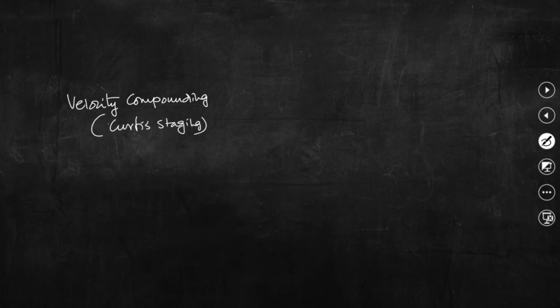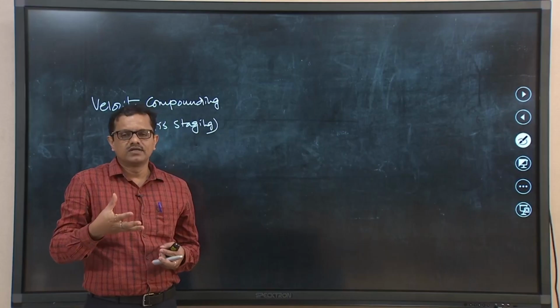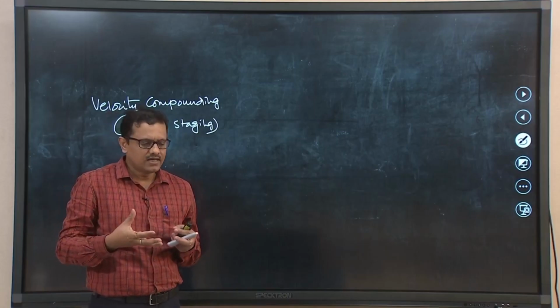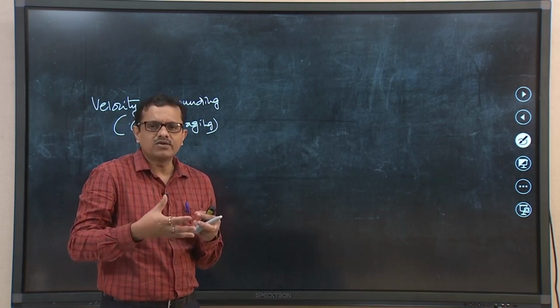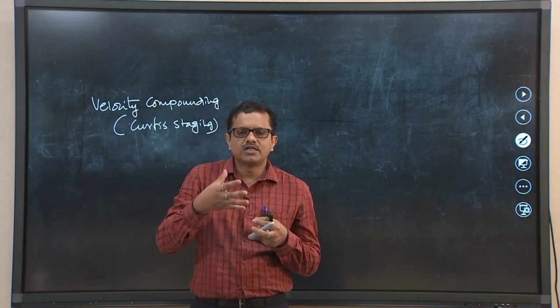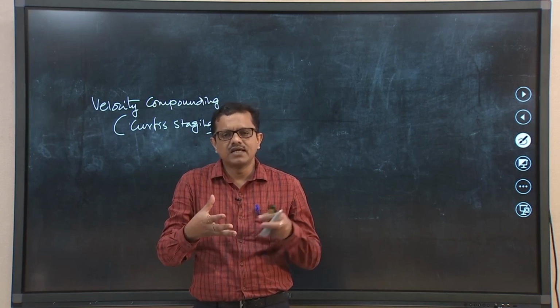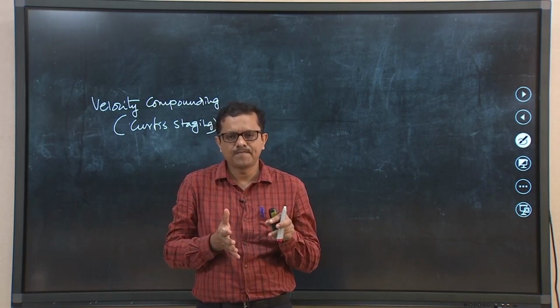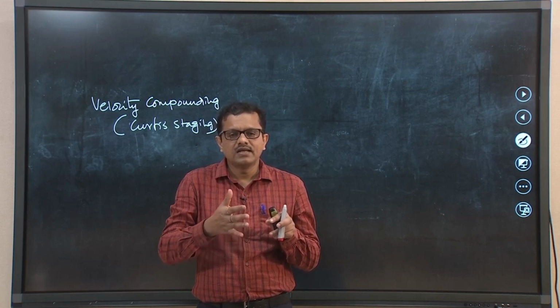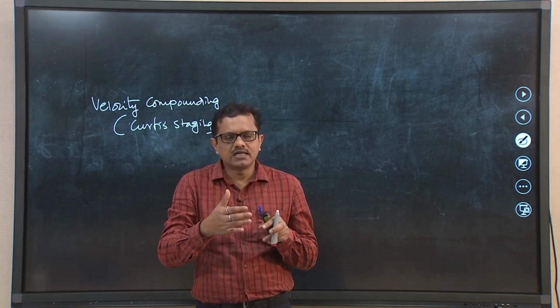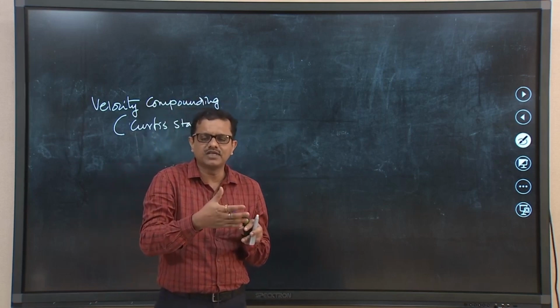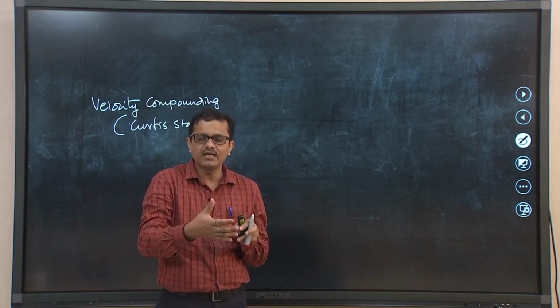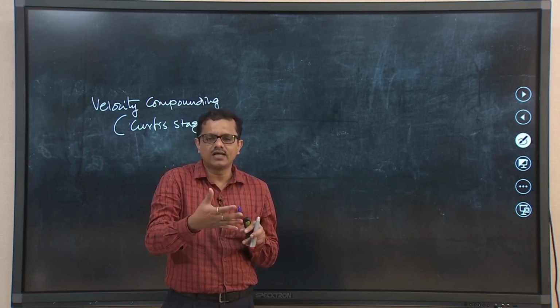So, try to understand, again velocity would be compounded. So, maybe what we can try, I mean, it would be possible to have the total drop of pressure in a first row of nozzles, and then the rise or increase in kinetic energy, increase in velocity of steam, that would be very high and kinetic energy will be very high.